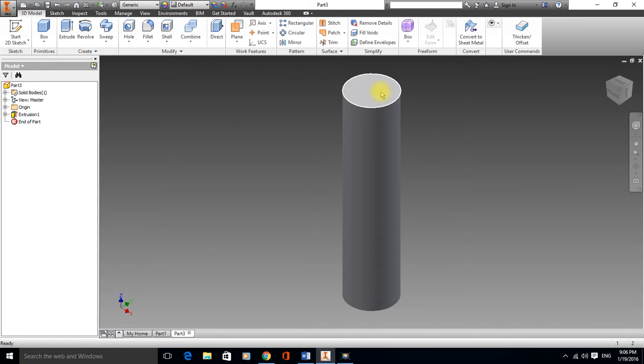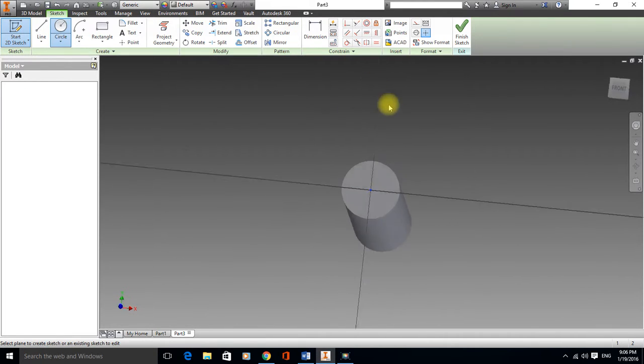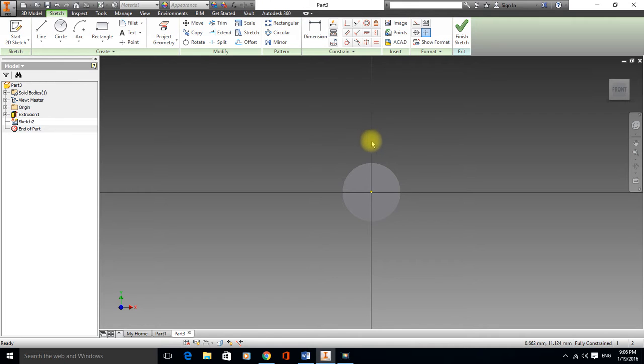I'm going to machine it this way round first. So it's another 2D sketch, and we're going to start it on the end. Now, we need to have symmetry here. Best way of maintaining symmetry is to put a center line in. So actually get line, select center line, and we're going to snap up from the middle, create a line, just hit OK, reselect line, let's just complete that line and hit OK. The length is immaterial, all we need is a complete center line running through the middle of the component.